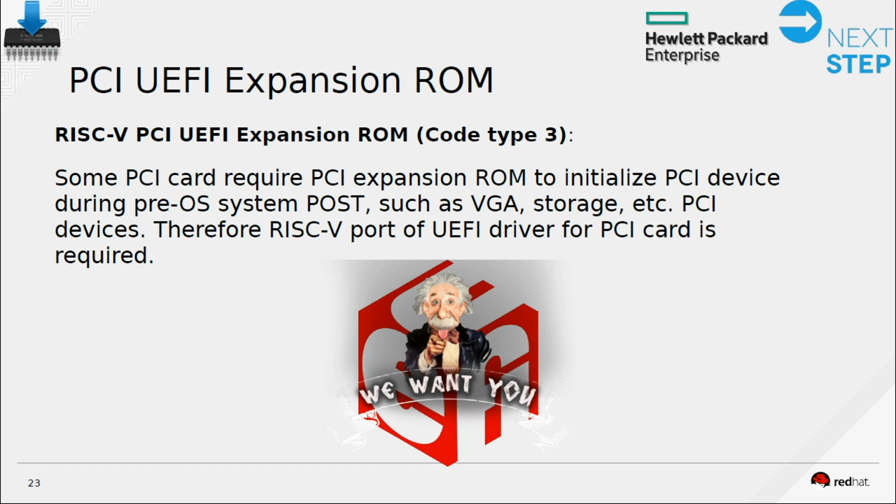Some PCIe cards require the PCIe option ROM to initialize the PCIe device during the pre-OS system POST, like some VGA cards, storage, and RAID cards. Therefore, the RISC-V port of a UEFI driver for PCIe cards is also required. This problem also exists in ARM servers. So right now, we need card vendors to put this RISC-V support into their PCIe cards.